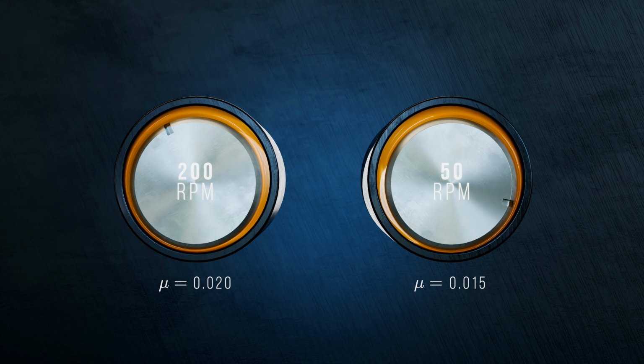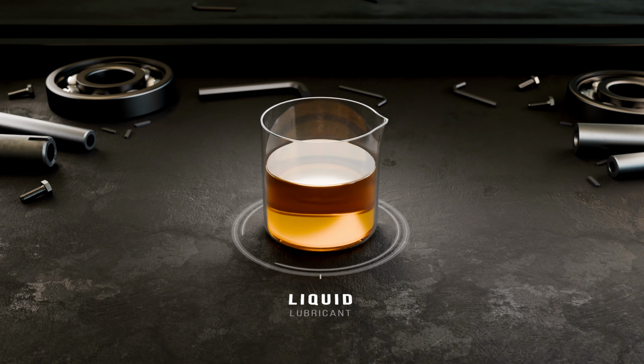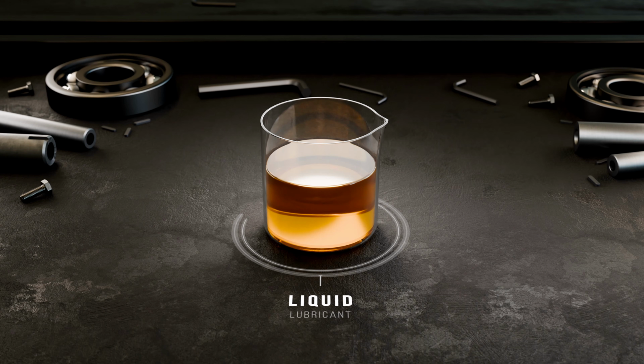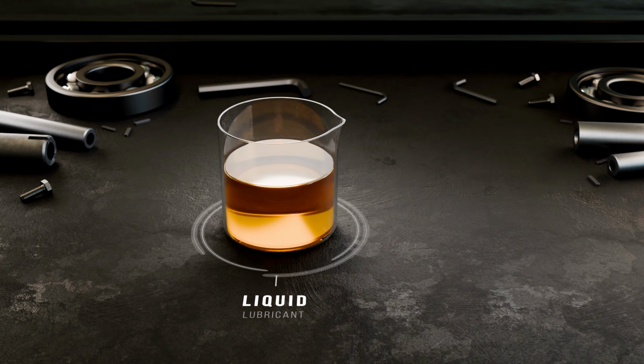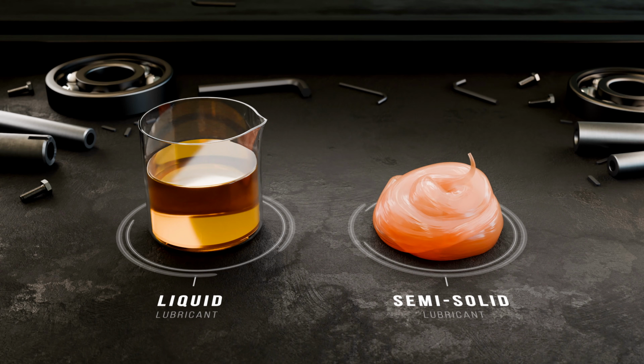Lubricants come in many forms, each suited to different operating conditions. Liquids, like oils, are ideal for high-speed machinery because they flow easily and continuously replenish the lubricating film between fast-moving parts. Greases, being semi-solid, perform best in applications where motion is slower or occurs only intermittently, or where the lubricant needs to stay in place without leaking over time. They tend to degrade more easily at high temperatures and high speeds than oils do.